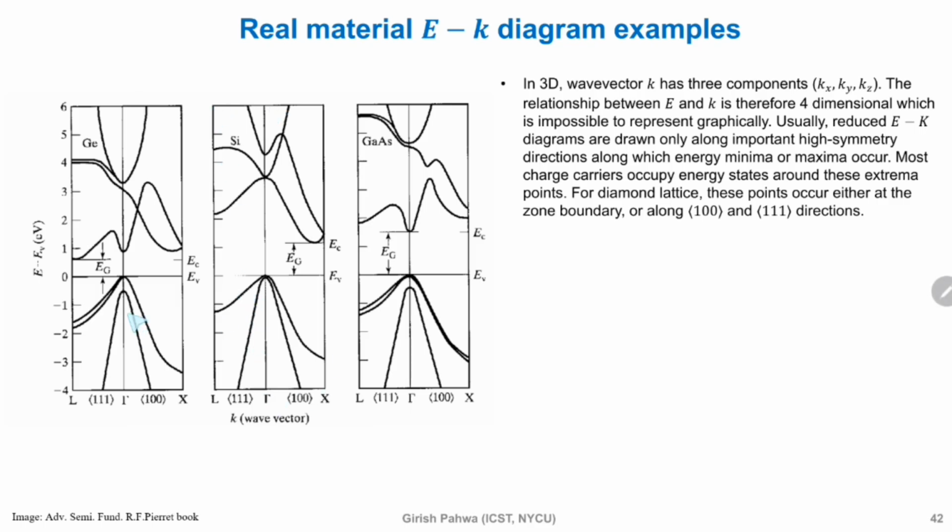What about silicon? For the valence band you have a similar type of structure; these two branches are totally merged here. You still have a split off band, but the difference is much smaller. So this is the valence band. What about the conduction band? So this is the conduction band, the lowest energy value.